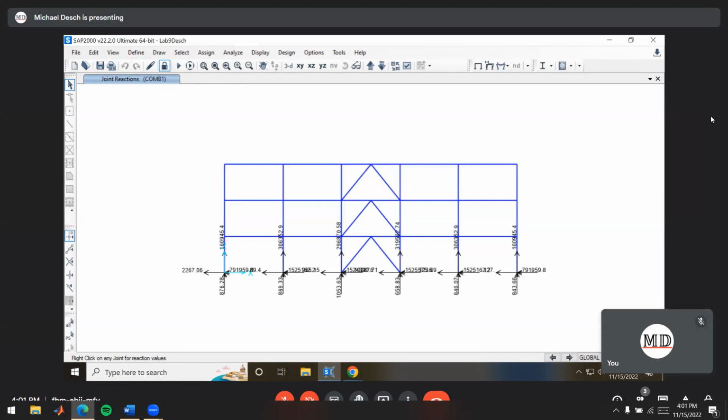So your loads are 144 times too big. That would probably do it. How do you remove all the loads? It's just easier to overwrite them. You could also just delete the plate element. That'll get rid of all those loads at the same time too. Either's about as fast.